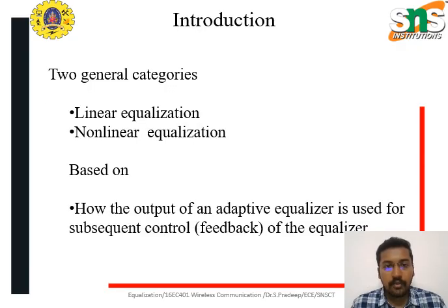Introduction. Equalization technique in wireless communication is a technique that combats distortions caused by the channel, particularly inter-symbol interference, and to improve signal quality. It works by reversing the effects of the channel on the transmitted signal, essentially making the frequency response flat. Equalization techniques can be broadly classified into linear equalization and nonlinear equalization with digital and analog implementations.